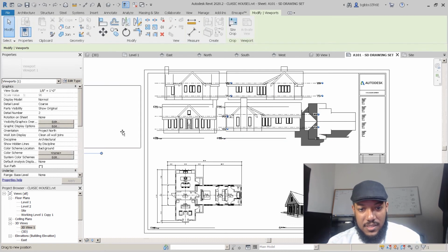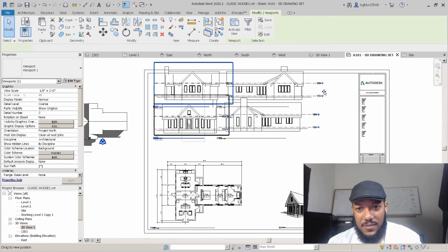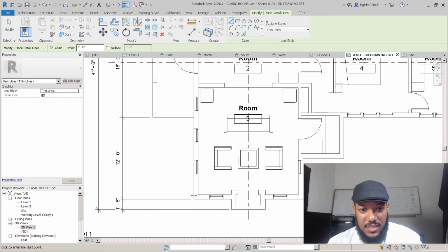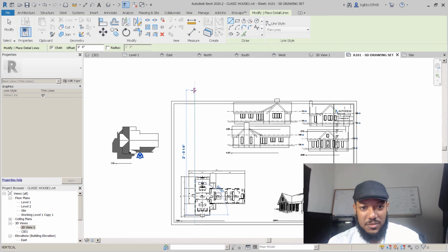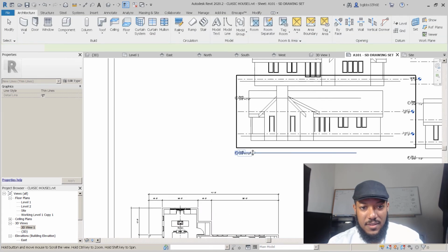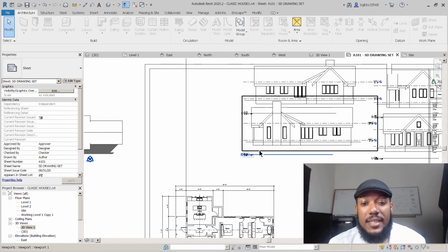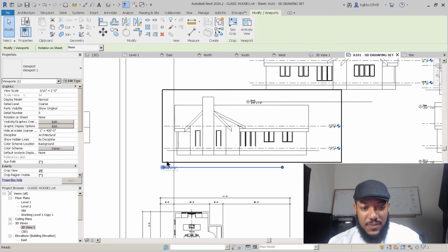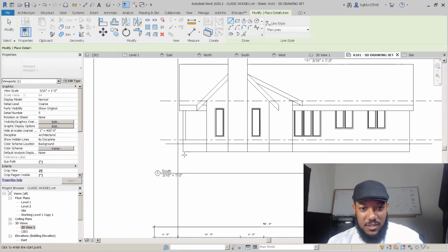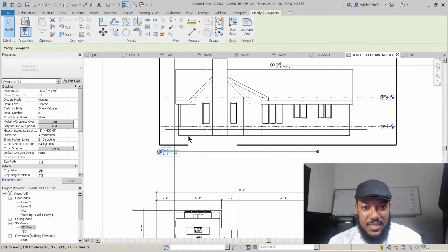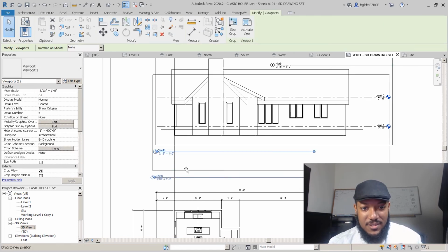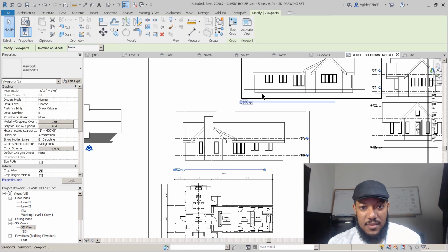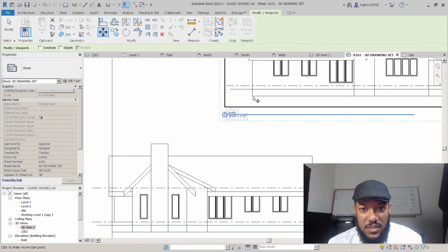And what we can do is line up our plan. And one thing to note is that you can't click to points in the equivalent of a paper space from AutoCAD. You cannot click on points like that in Revit. Like, I can't click on that particular point, so be mindful of that. It's a bit of a fail-safe, I guess, so you won't be going back and forth like in CAD. So yeah, use a line to align these, and move in this one as well.